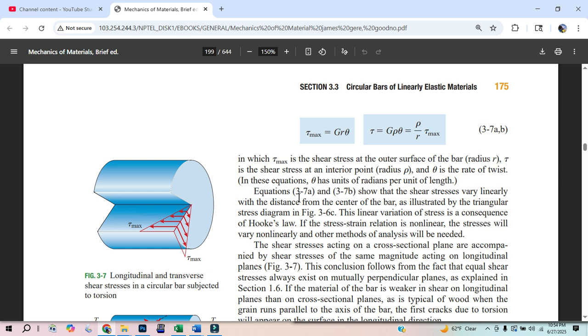This face is still facing that direction axially. But when I'm trying to shear it, I'm actually putting the force perpendicular to the direction that face is facing. And then I'm putting a downward force over here. So whatever force I'm applying up and down, and the area of that face, is going to dictate what this stress is. The stress is in units of force per the area that's getting sheared.